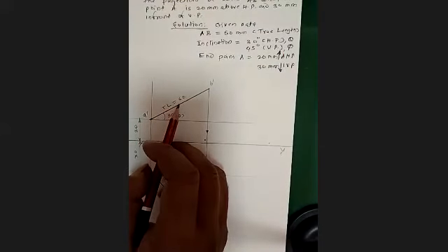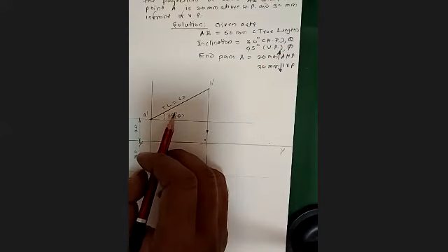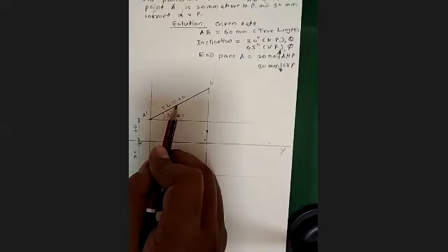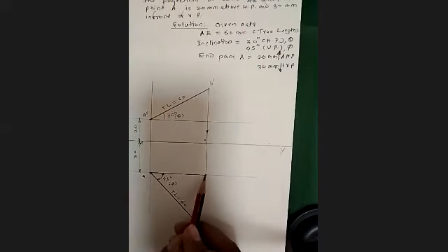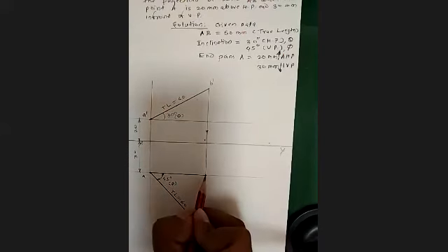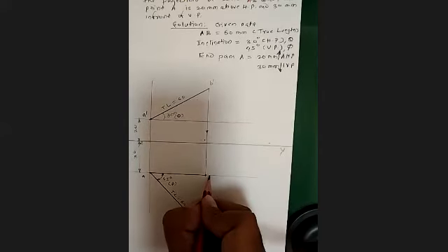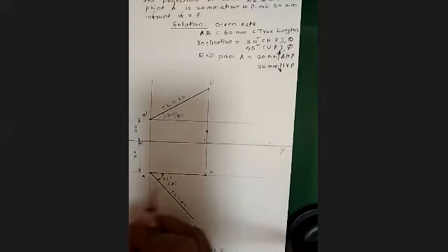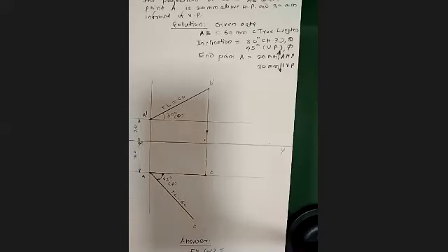If this is the true length and we consider the line inclined to HP and parallel to VP, then this will be the front view and this becomes your top view, or we can say the plan, right? So the length from this A to this point, by taking the projection, suppose I name this point as B. Okay. Notation I will change, modify it accordingly.